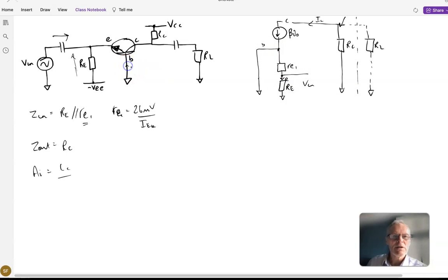Remember we've got this sort of beta current coming in here, so this is going to equate to the IE plus the IB, so that's going to be approximately 1. It's going to be just shy, it's going to be short because of this small base current, so yeah, 0.999 in value.